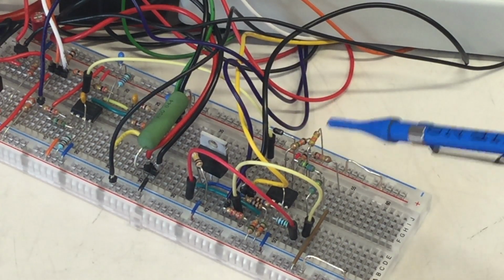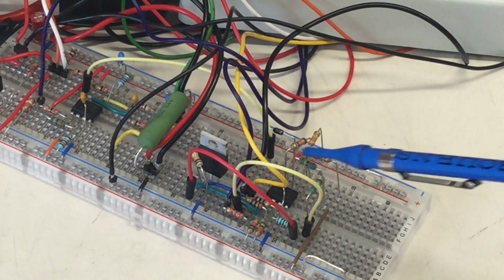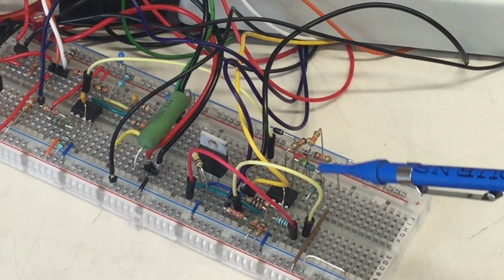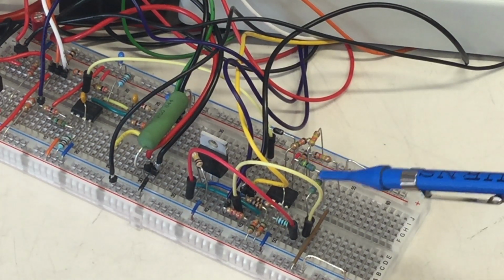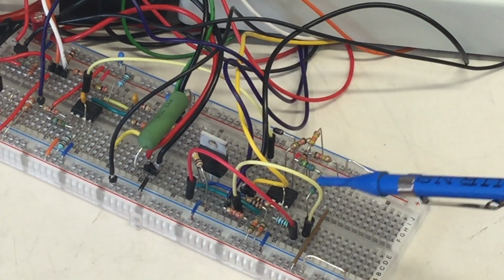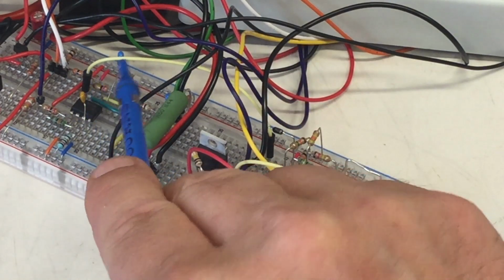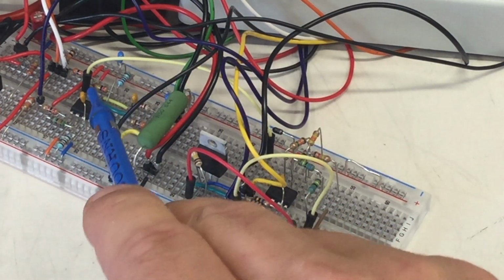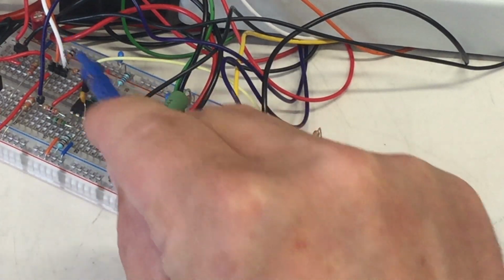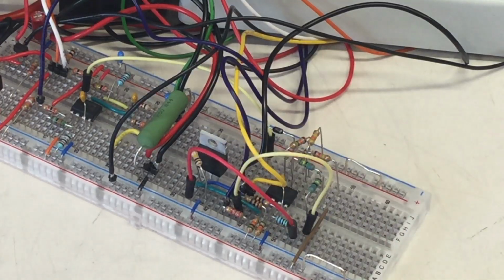If you count, there's one resistor too many there. That's because I don't have a 15 meg ohm on hand, so I have two 7.5 meg ohms in series. And that light yellow cable here that goes over to the diode goes off to my current regulation voltage divider. Let's power it up.